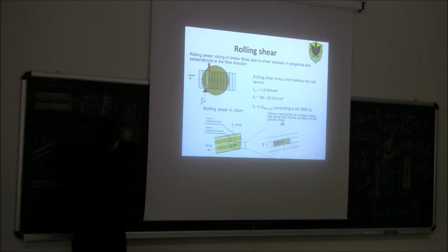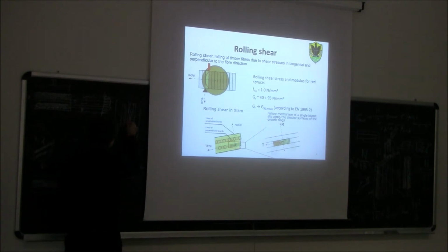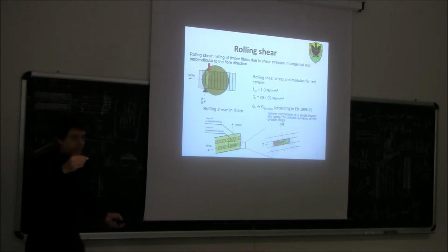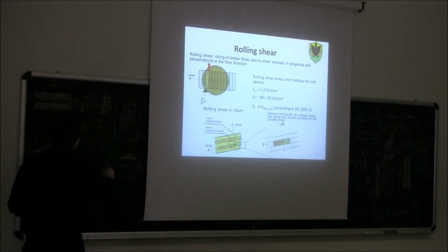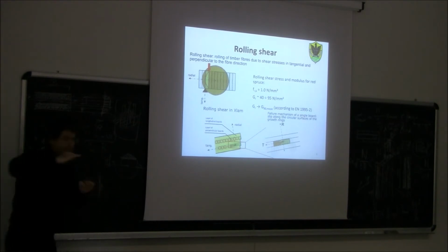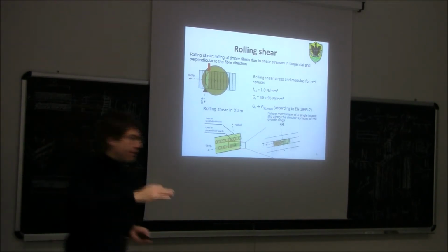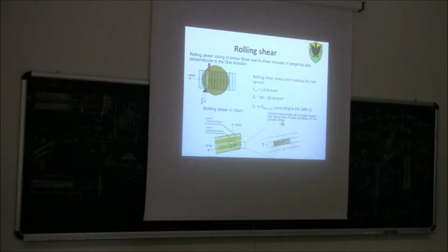So this is in some way the micro model of wood. And we said that these fibers here are very strong, but this matrix, called middle lamella, is very weak. So we said that if I have a shear, for example, around this plane, so if the shear plane tends to cut the fiber, then the strength is very big, because the shear resistance depends on the strength of the fiber.